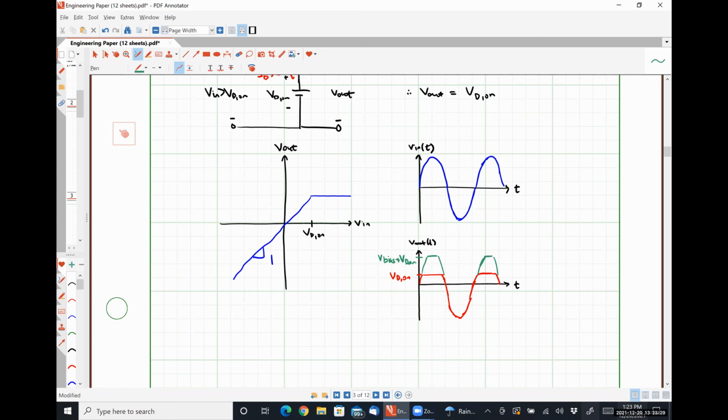These bias clipping circuits are used a lot to eliminate noise, so spurious signals that are superimposed on top of something that we want. This is a way for us to limit effectively like an inrush signal, where we expect things to normally be at a level of around, let's say, 10 volts, but noise could push it up to 12. Well, this keeps everything 10 or less, which is safe for the operating point of the system. Okay, so these are our limiter circuits, all right?